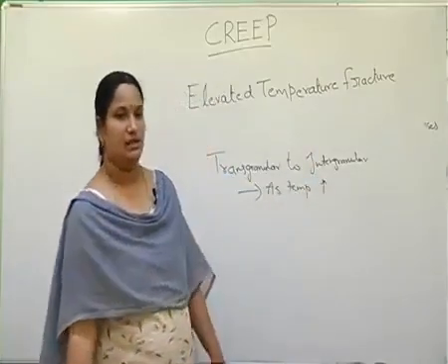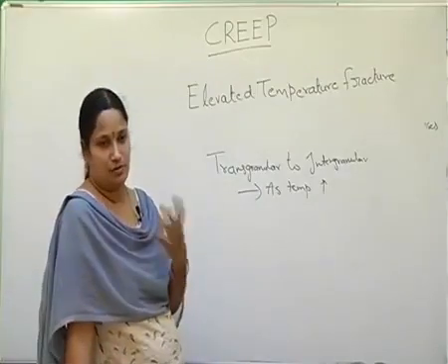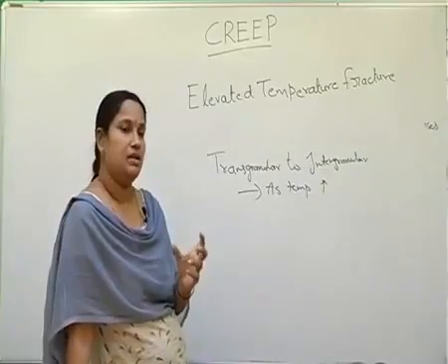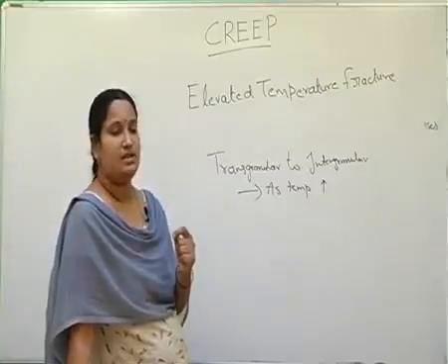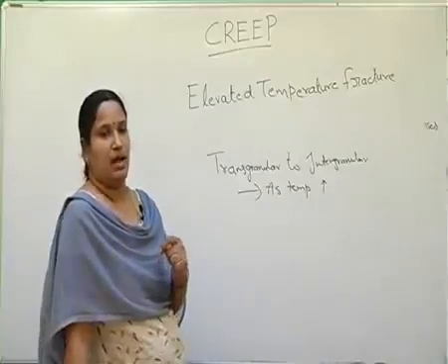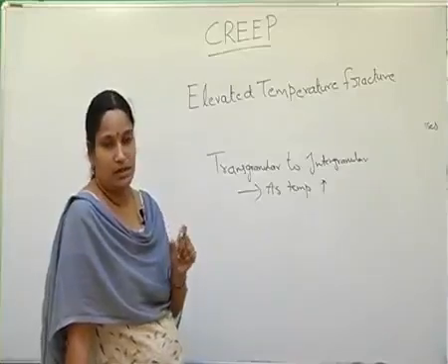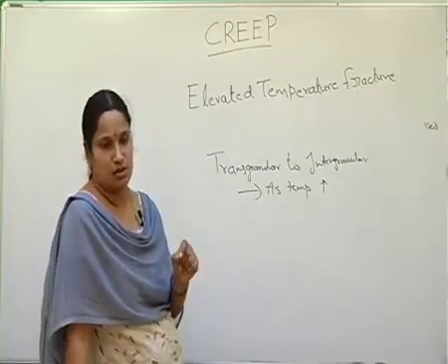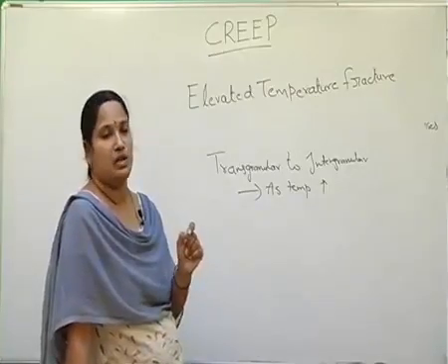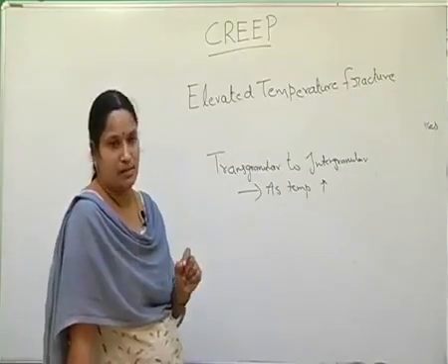This can be stated in a way that at low temperatures, grain boundaries are stronger than grains. Therefore, a fine grain size material is stronger when compared to a coarse grain size material. And at higher temperatures, grain boundaries are weaker and grain interiors are stronger. So a coarser grain, which has a very small grain boundary area, performs better and is stronger than a fine grain size material.